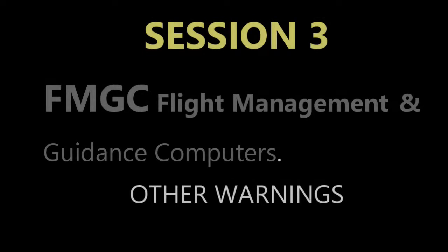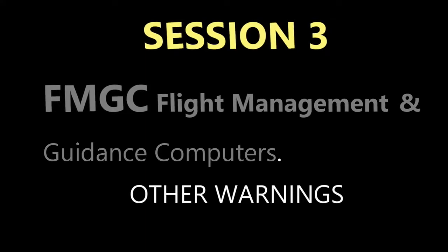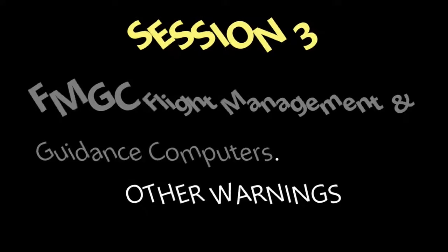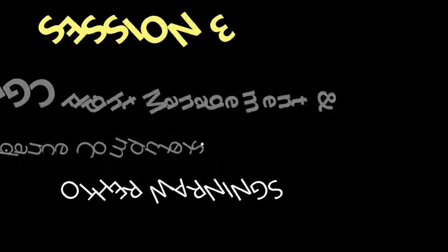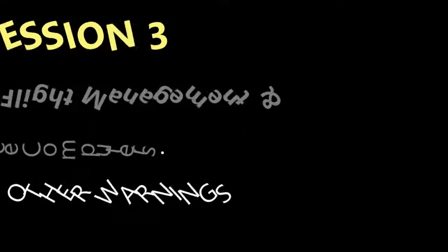So you're going to have one that's 100 above. What that means is that the callout 100 above is given when the radio height falls to the selected DH plus 100 feet. That's where that 100 comes from. So it'll either be 100 above or minimum. Those two are the warnings involving the decision height. And then the other thing is altitude alert. It takes the difference between the aircraft altitude and the reference altitude selected on the FCU, whatever reference altitude was used.